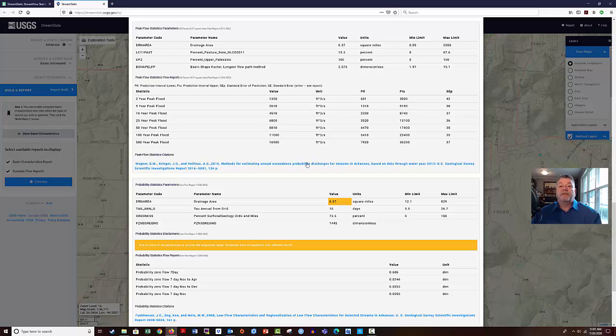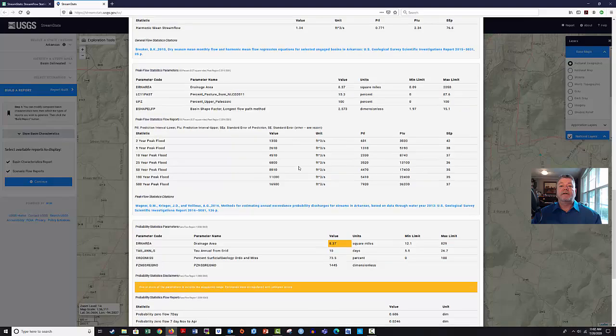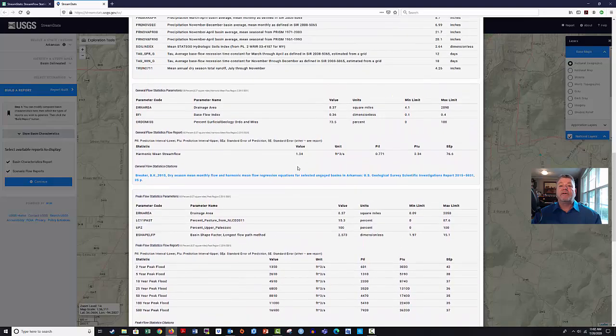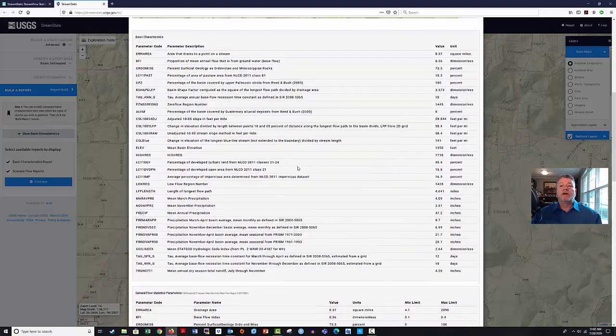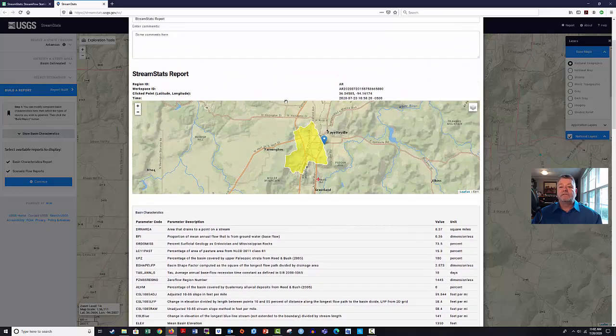This is important because from here we can build a unit hydrograph that we can then extrapolate to any rainfall event to build a runoff hydrograph based upon any rainfall event in this basin. I hope you enjoy this. This is an incredibly powerful tool. Several years ago, I couldn't have used this tool because it wasn't available. So I want you to be effective users of this tool as good engineers. We will pick up with unit hydrographs in our next lecture.